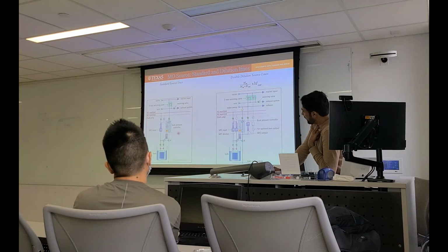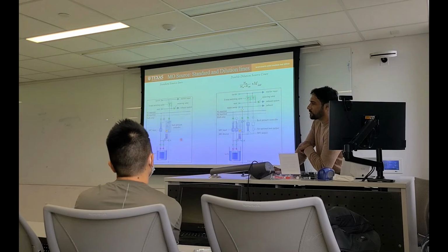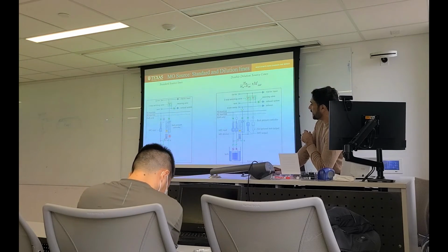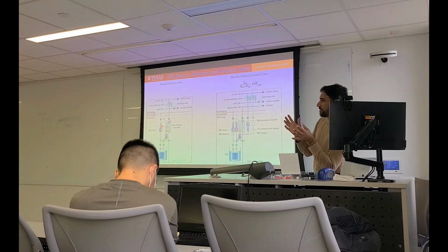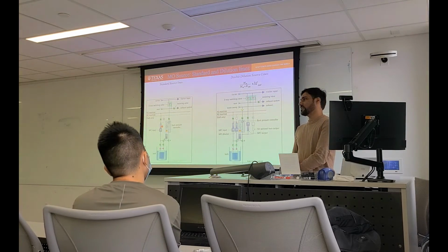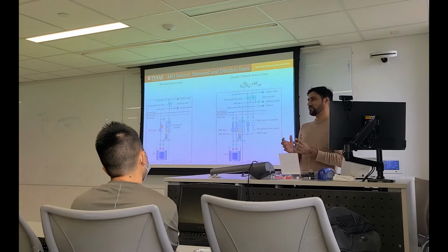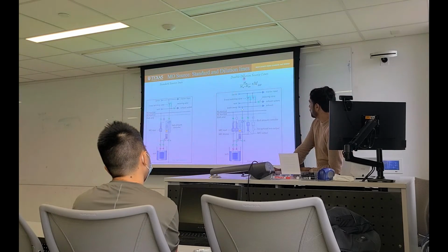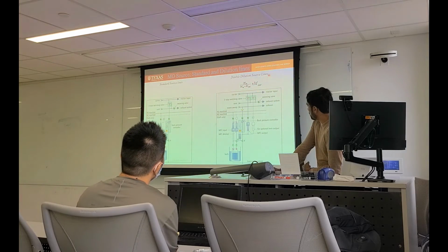This exhaust is different and the baseline is different. Baseline is also connected to the exhaust, but it is only used when we have the dilution line. So don't mix up the baseline with the exhaust. Baseline means you have diluted your source with the carrier gas, and the total flow is higher than you need. You can just throw the remaining source to the baseline. So this is the double dilution source line.